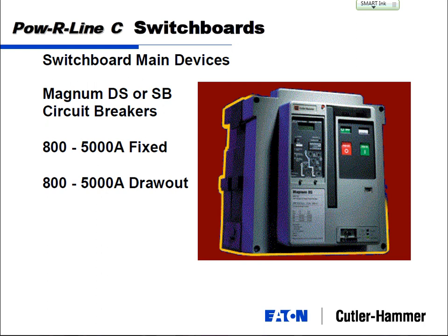However, I can also put a little motor operator inside here that can automatically charge the spring, and that's what makes the breaker electrically operated. So when I open the breaker, the motor operator charges the spring. I can close the breaker and open and close it, and every time I'm continually charging the spring. So I don't need to be in front of that breaker. I can stand at a push button station on this wall and open and close that breaker over there.